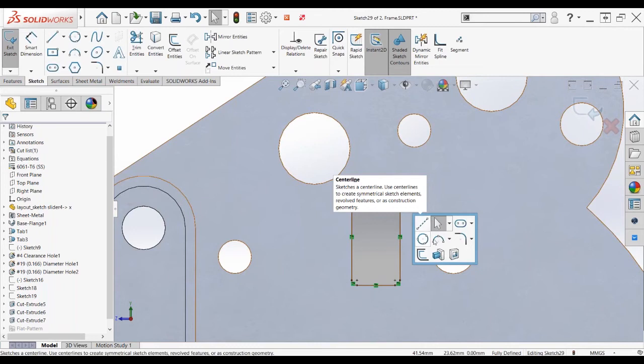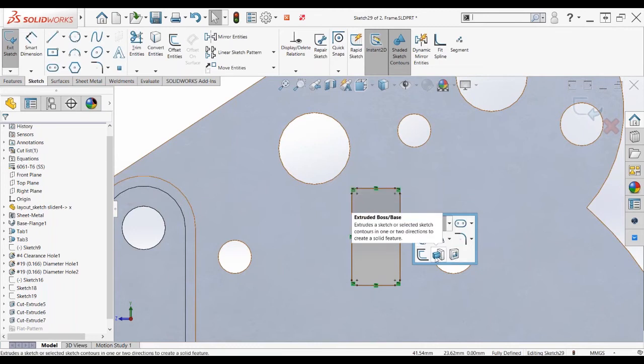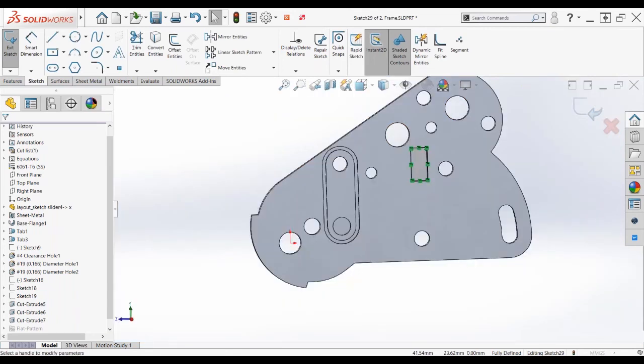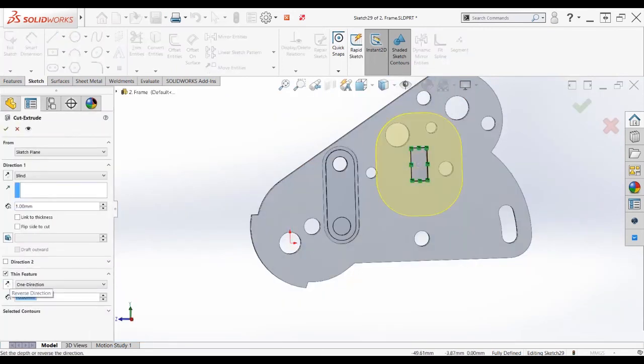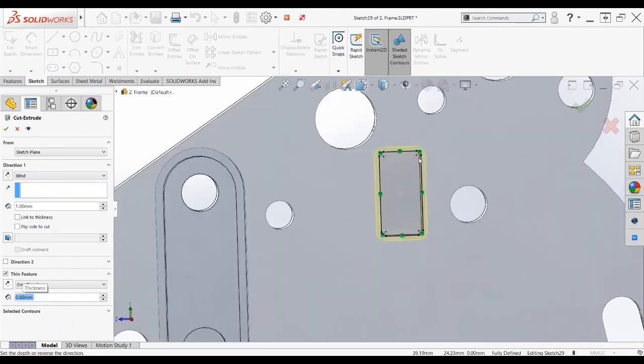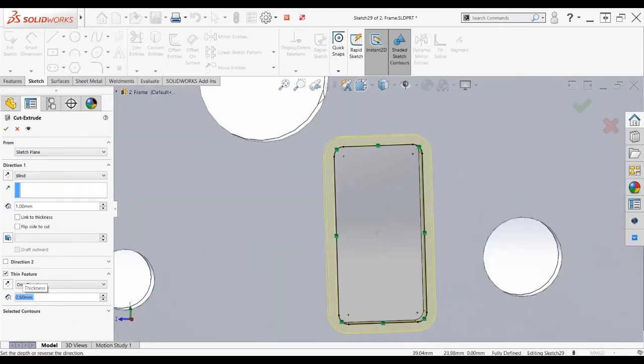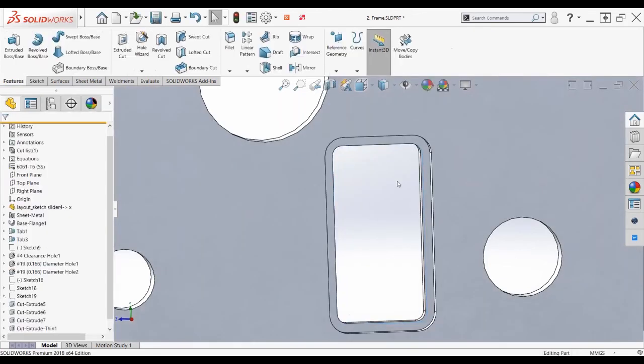I have also put in a couple features as well. So I put my extrusion and my extruded cut in that menu, and that saves me from having to go up to my command manager, mouse wheel to the features and click on the feature that I want. It's all right here at my fingertips, making me really speedy and really productive. So I'm just going to cut a thin feature to make a nice little groove. And there we go. I have slotted myself out a groove.